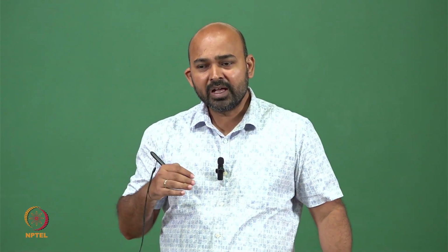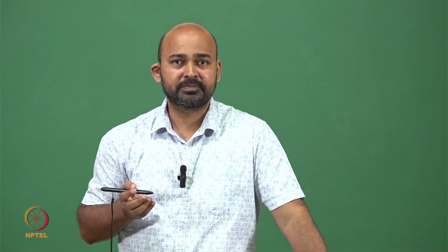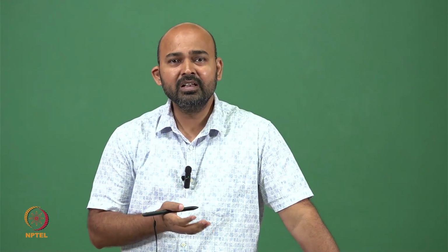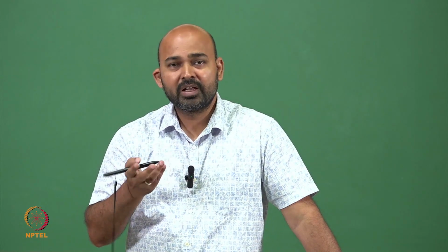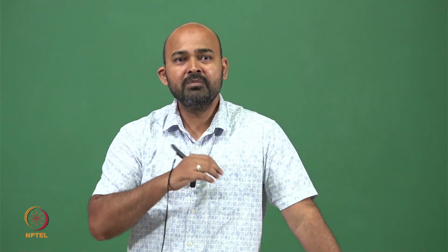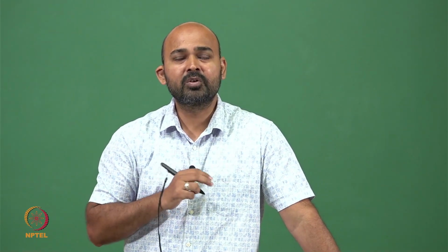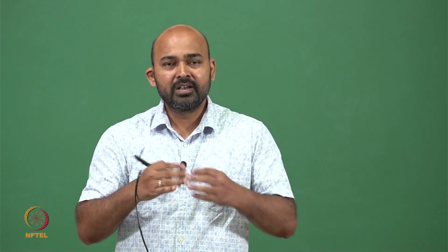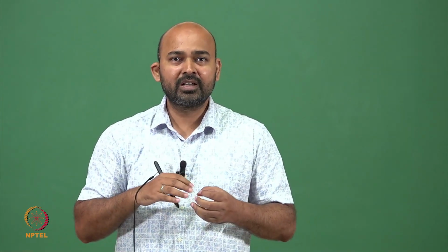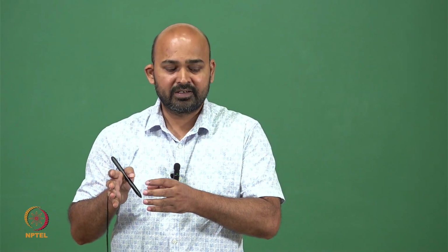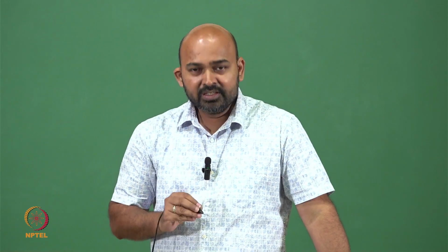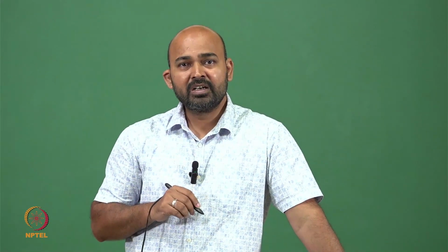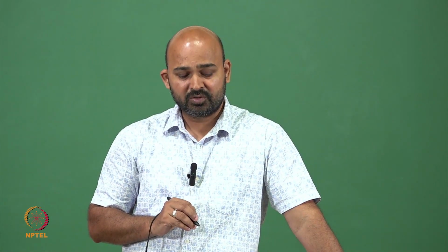It means the semiconductor, whatever voltage we apply, cannot conduct. So depending upon external factors, this material can conduct, become like a metal, or become close to an insulator. It can conduct the current or not, based on the external factors. So this is called a semiconductor, and typically the band gap of a semiconductor is about 1 electron volt.